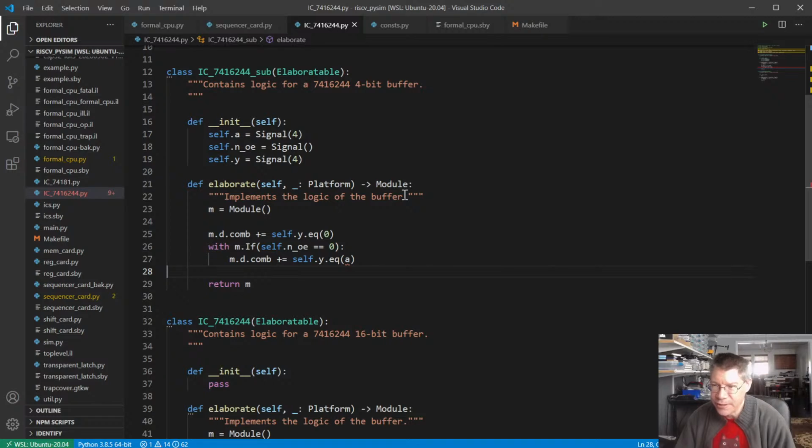However, with hardware, I typically use formal verification, which is a lot better than unit tests because formal verification tests all possible scenarios, not just the 1 or 2 that you can think of. Now, yes, you could design a test bench with delays in it, but again, as long as you keep in the back of your mind the timing requirements, I think it'll just be fine.